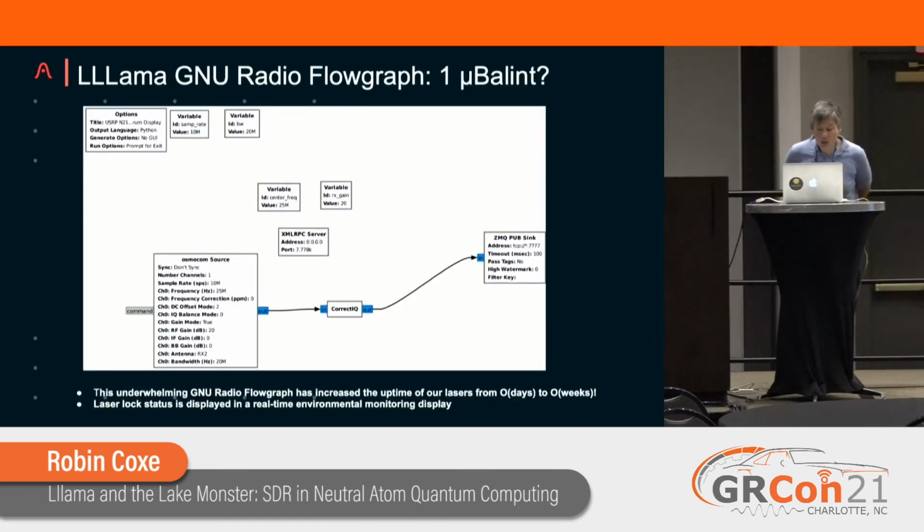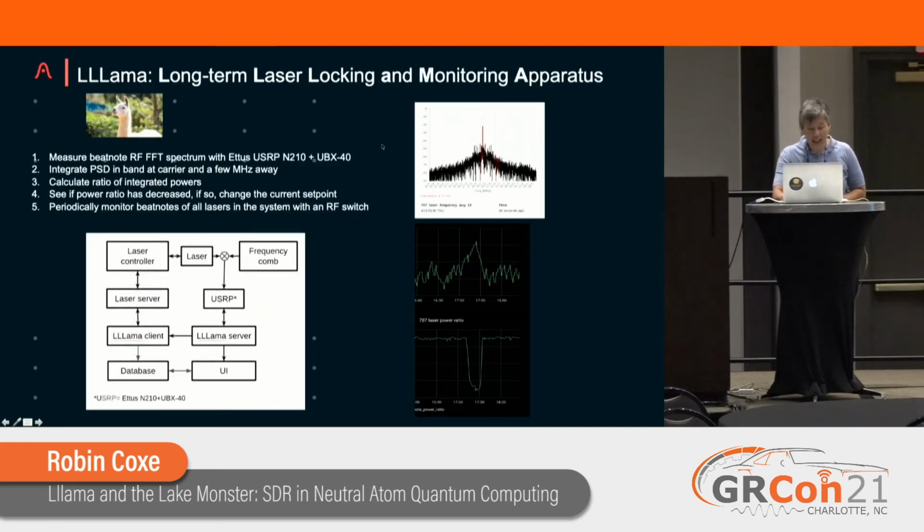So no talk at GRCon would be complete without a flow graph, and this is a very underwhelming one, but it does have Mike's correct IQ block in it. We're not actually taking the FFT in this GRC block. When we were originally prototyping, we did, but the FFT is now actually being run on the host PC, and it's being fed into our real-time environmental monitoring display.